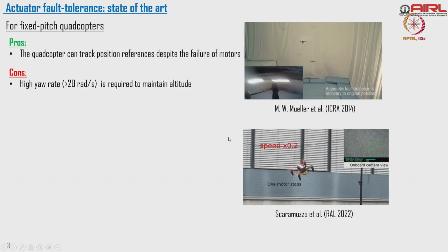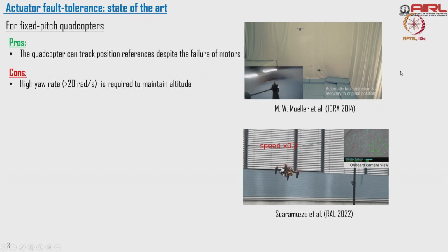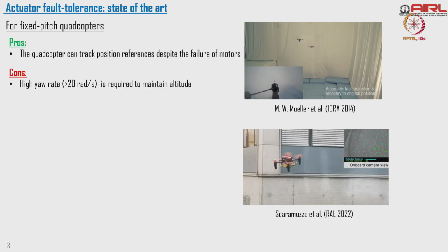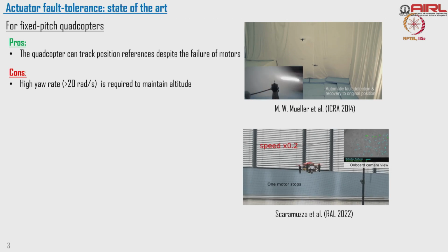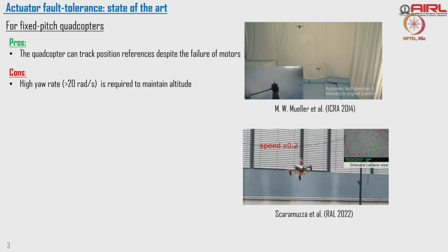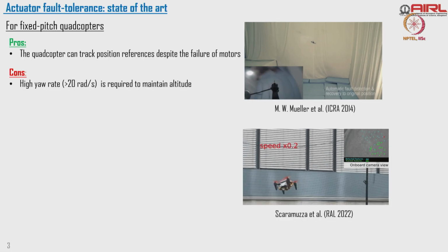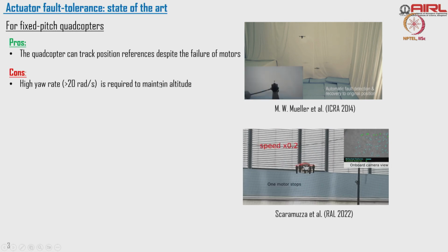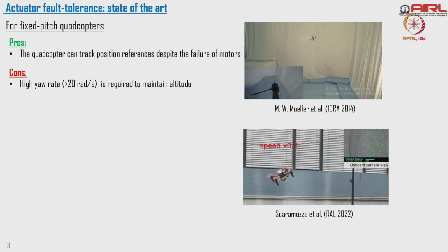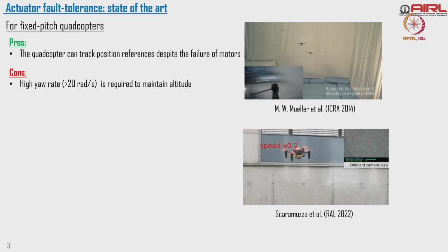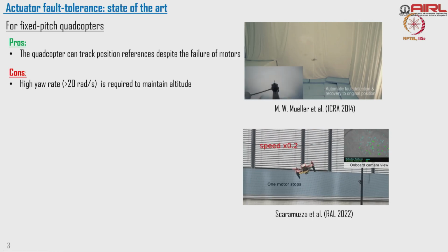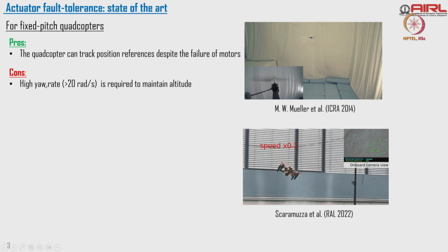Now, what is the advantage when we talk about actuator failure? Okay. See, complete actuator failure is a challenge in a quadcopter. If you use a hexacopter or octocopter, you have redundancy. With that, you can somehow provide yaw stability and make it land. The moment one of the motors fails, you get into a yaw or spiral motion. You can land safely with the spiral motion, but you will never be able to achieve the necessary attitude control if you want to continue the mission. That is one of the bigger problems, right?